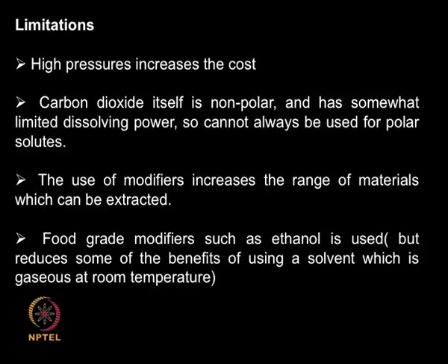But there are limitations also. If you are going to use very high pressure, your equipment also has to be very high pressure. That is one of the disadvantages. The capital cost of a supercritical unit is high, so you need to recuperate the capital cost. CO2 is non-polar and has very limited dissolving power, so it cannot be used for polar solutes, meaning solutes which are hydrophilic in nature. So you need to add some modifiers. Ethanol, for example, is used as a modifier. Generally for food grade, ethanol is the only solvent that is allowed.